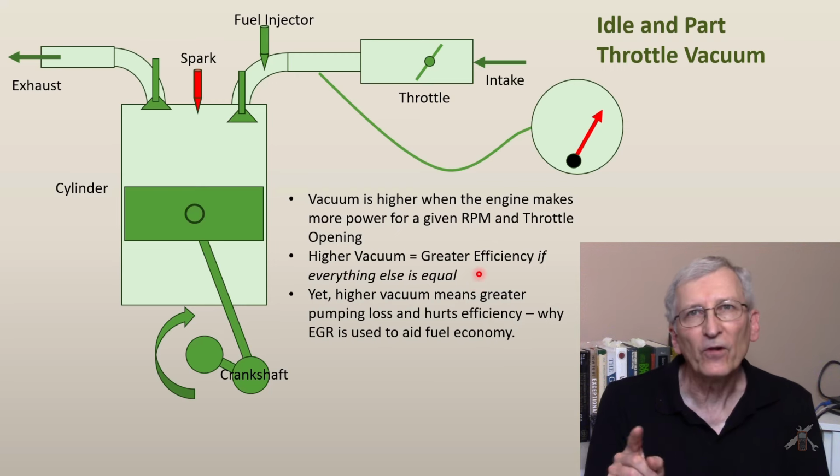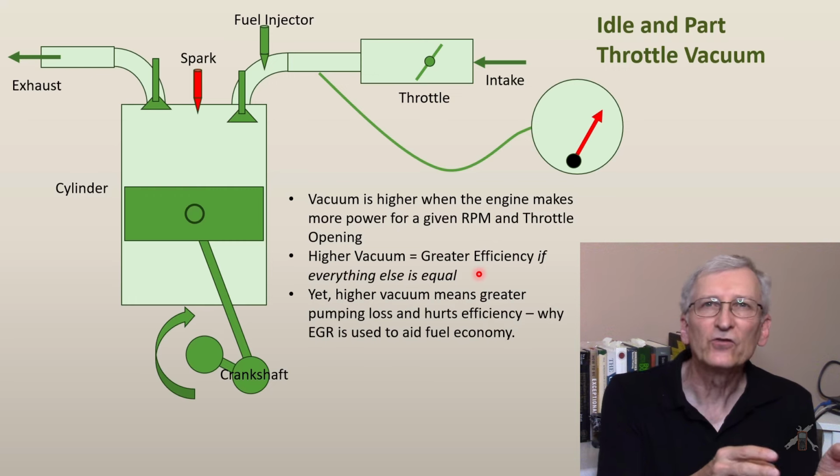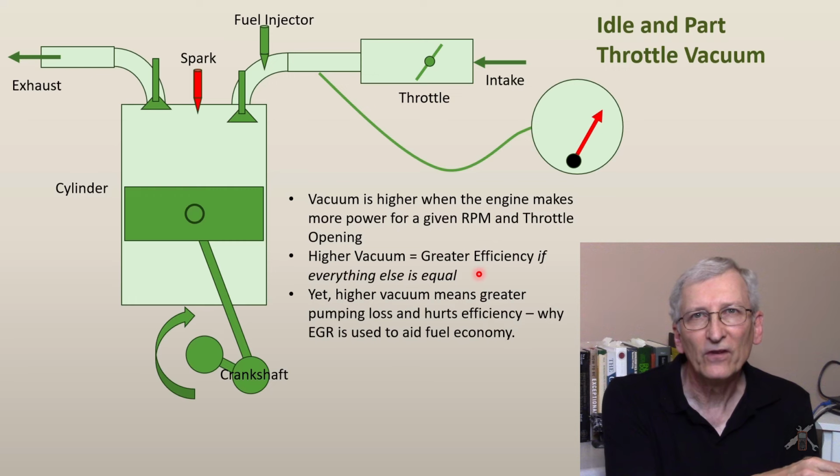Now, the flip side of having high vacuum is that your engine is pulling against that vacuum, and it's called pumping loss. The fact that you have vacuum in the first place actually hurts power. It's a paradox of sorts.